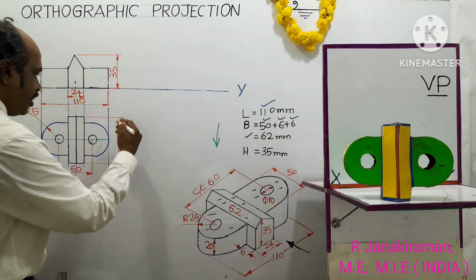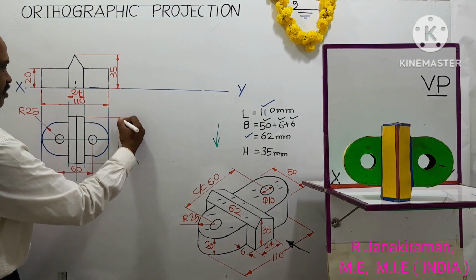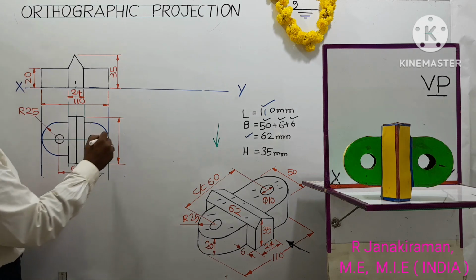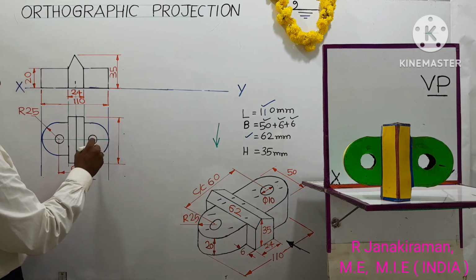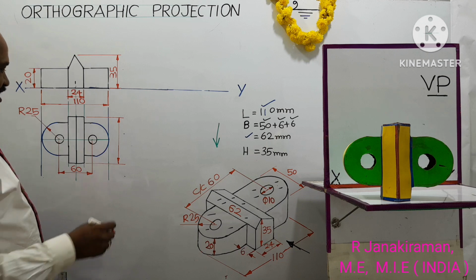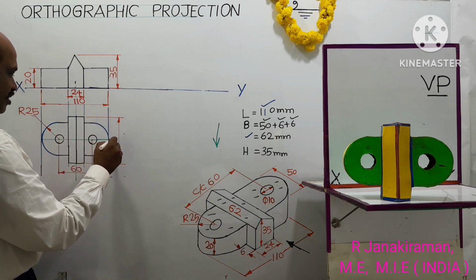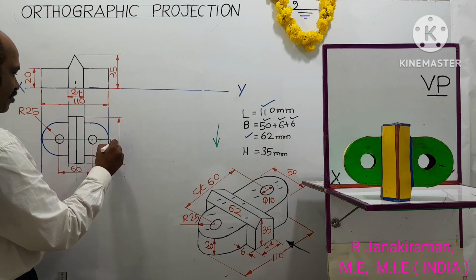Provide two narrow arrows and shade them. The dimensioning work shall be done by HB pencil, thin HB pencil lead. Writing work shall be done by HB pencil, appearing dark, so that one who reads the diagram can see it clearly. 62 is the maximum breadth of the object.